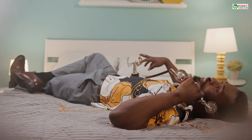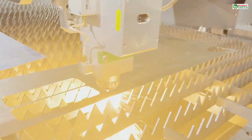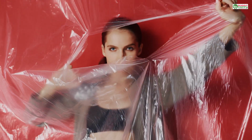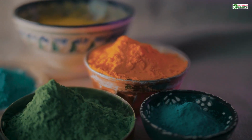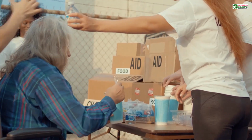It just won't. Finally, there's the industrial powerhouse, selective laser sintering, or SLS. This technology uses a high-powered laser to fuse together particles of powder, like nylon or metal. A huge advantage of SLS is that the unfused powder around the object acts as a support structure, so you don't need to add those little tree-like supports. But that doesn't give you a free pass on wall thickness.